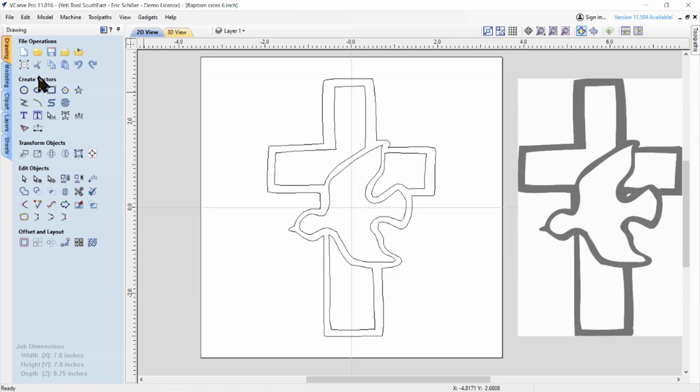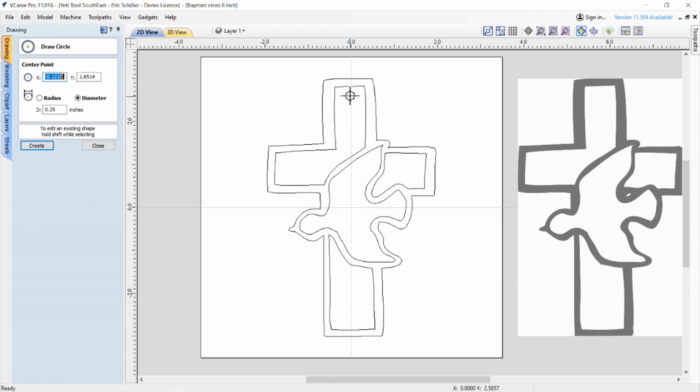They were going to use this as a hanger, a Christmas ornament on the tree. So we need to put a hole in it so we can run our hanger through it. Now when we do this, we see both the crosshair and the circle. I'm going to make this a 0.28 because I'm going to use a 1/4 inch tool, but I'm not sure what the bottom of the tool looks like. Is it made for drilling operations like a mortising bit, or do I need to go a little larger than that and let it circle its way down? I'm just going to leave this at 0.28, 0.3, whatever.